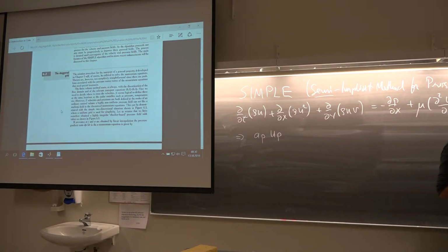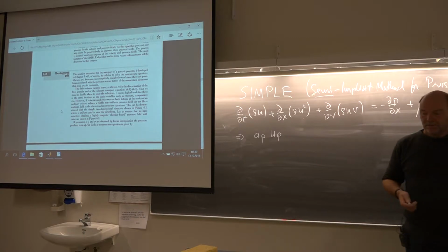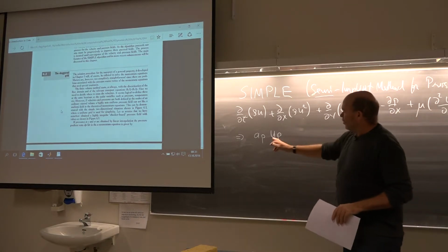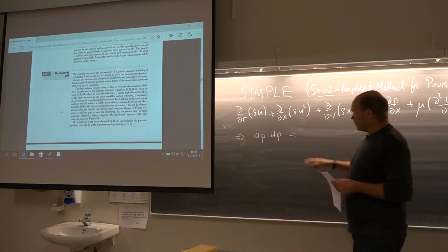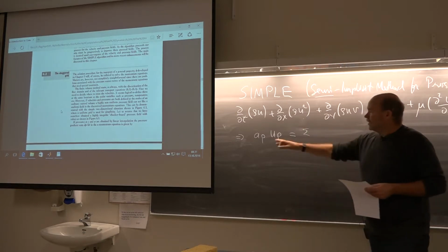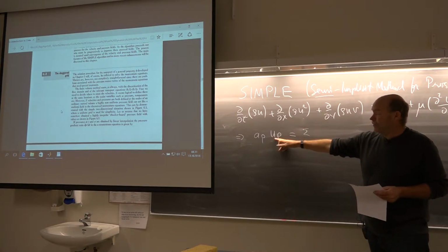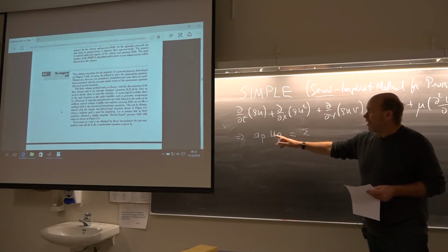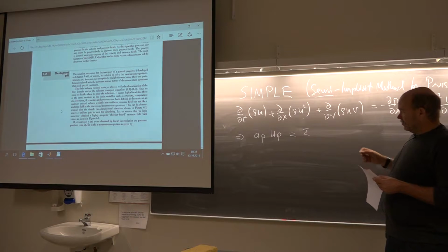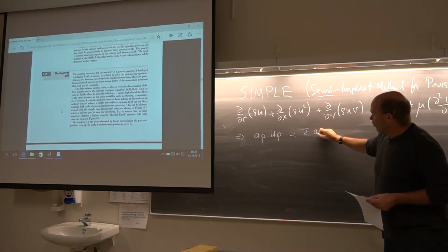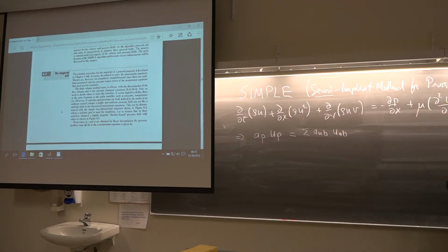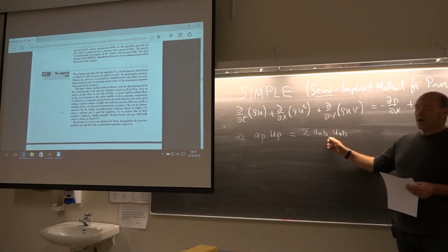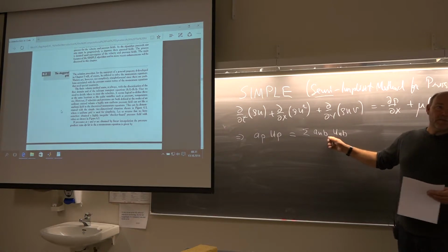So, no, they are not necessarily the same. But forget about that. We just say that yes, we will have a whole bunch of algebraic equations like this, and typically the center point unknown velocity at point P multiplied with its coefficient AP equals now the sum of all the neighbors, the neighbor velocities, and depending on the number of dimensions, 1, 2, 3, it can be a whole bunch of neighbors. And if you have an unstructured mesh system, it can be very many actually.